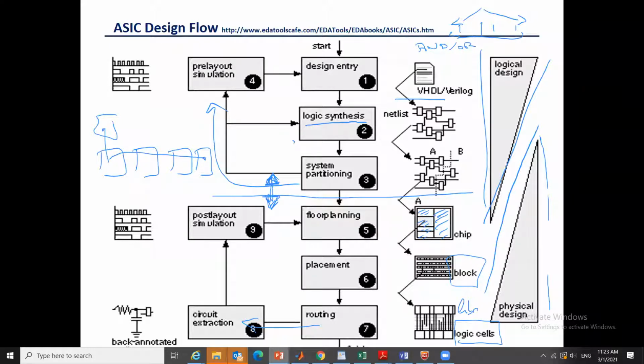We are studying the layout for two reasons, because there is something nice about the unit path and optimizing how things are connected, just to give you an idea for the stick diagrams, and also because later we are going to look at the impact of the parasitics of the wiring, and we're going to study the basics, the simple RC, but how this affects delay, and then look at the delay of the intermediate circuit and stuff like that. These are all just to give you an idea how designers use rule of thumb, rough equations to decide, and then they plug them into these big tools, and those big tools take care. And you have to give a good initial condition and pick up from there.